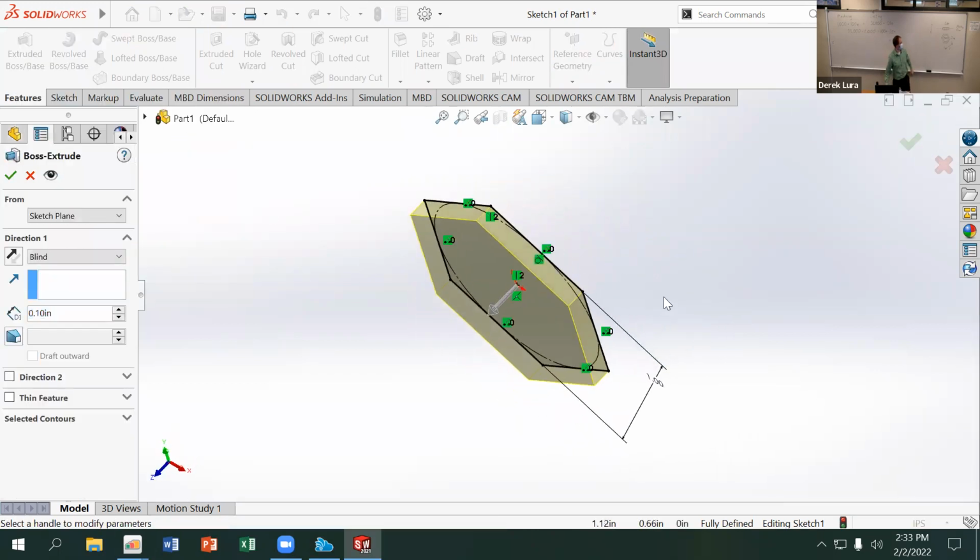And again, I want the middle of my part to be where the parting line is. Because again, if I put that parting line in the middle, then it decreases the amount of distance I have from the edges of my pattern to the center, which makes it easier to pull out. Something like this, you might not care that much because I could have a very simple flat face on the opposite side if it was just a token like that. But if I'm having any geometry at all on the top and the bottom, I really want to have that in the middle, right? Because it's going to make it easier to do, and I'm going to have complexity inside those molds either way.